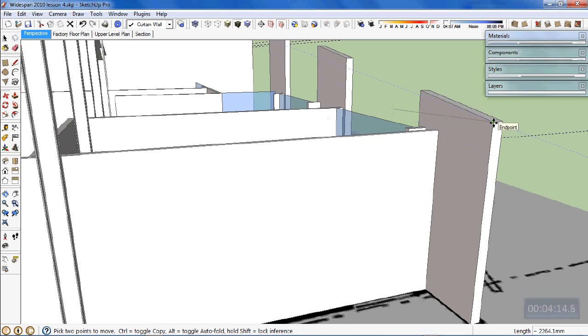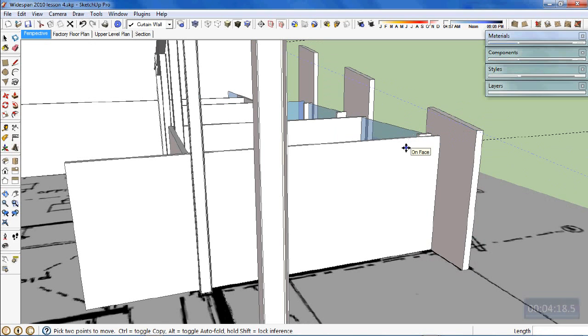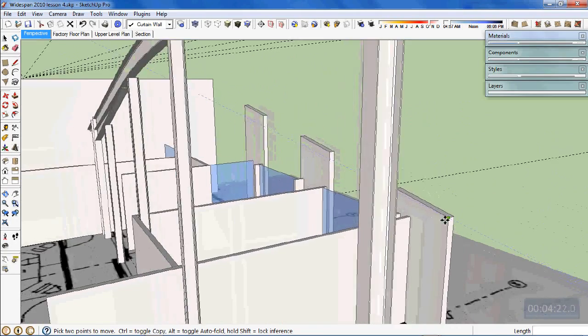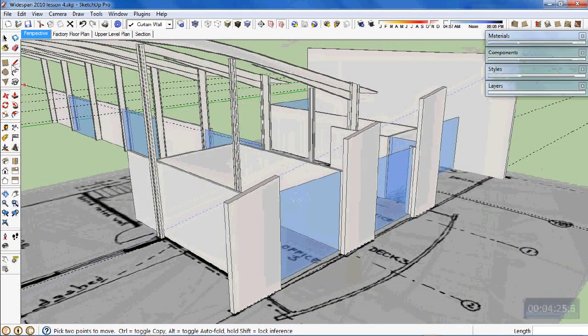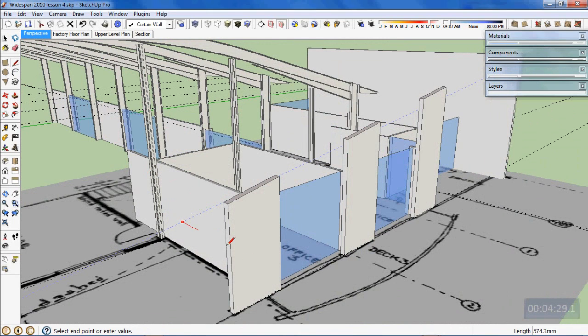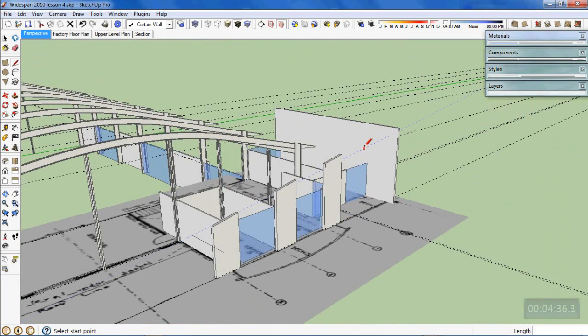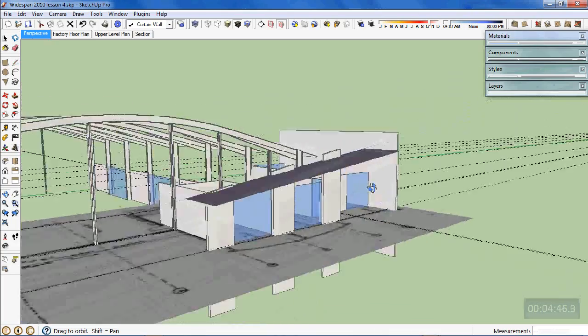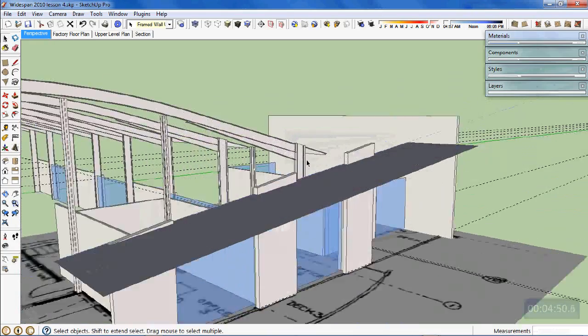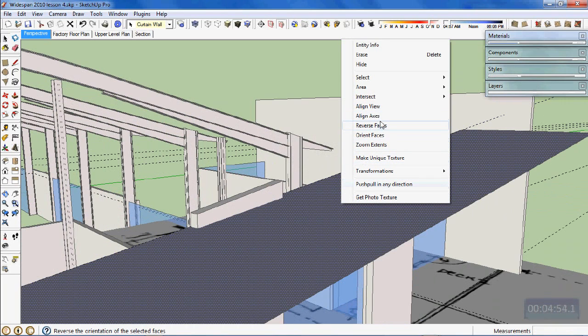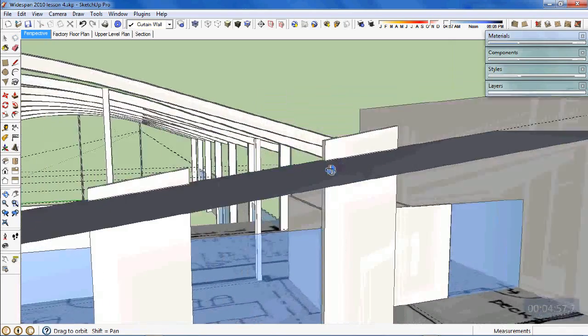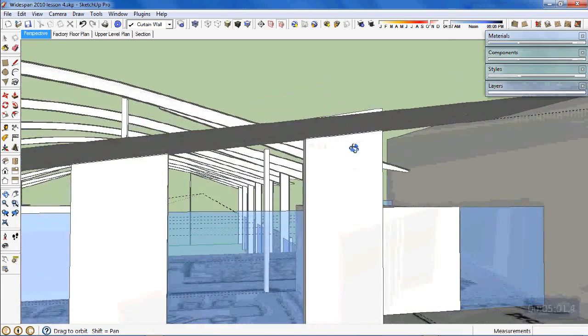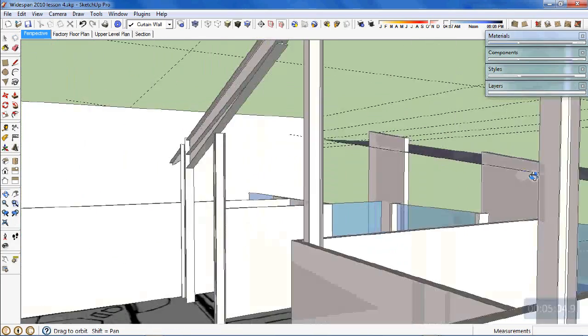And so now our job is to start trimming up these concrete tilt-up parapets along that line there. An easy way of doing that, we've done this sort of thing before, was I might come along there anywhere in red axis direction, as long as it's in red, and then I can close up the ends of those lines and then close up where they started from. So that will give us the plane that everything needs to be chopped off at. So we then select that roof plane, and we intersect with model, which means we've now created intersecting lines at any of those points there. Which means if I can get myself orientated nicely, maybe back in this direction, I might be able to make a selection in one go.